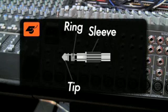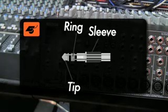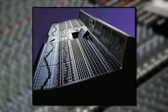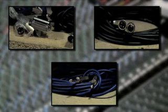This type of connection is unbalanced due to the TRS jack having to share only 3 conductor points for both lines, as opposed to 2 conductor points per line with a balanced jack. The TRS jack insert typically uses the tip as the send and the ring as the return. Some setups have the tip as the return and the ring as the send. High-end consoles generally have discrete inserts, send, and returns. This allows for balanced connections and can be supplied via D-sub connectors, XLRs, or jacks.